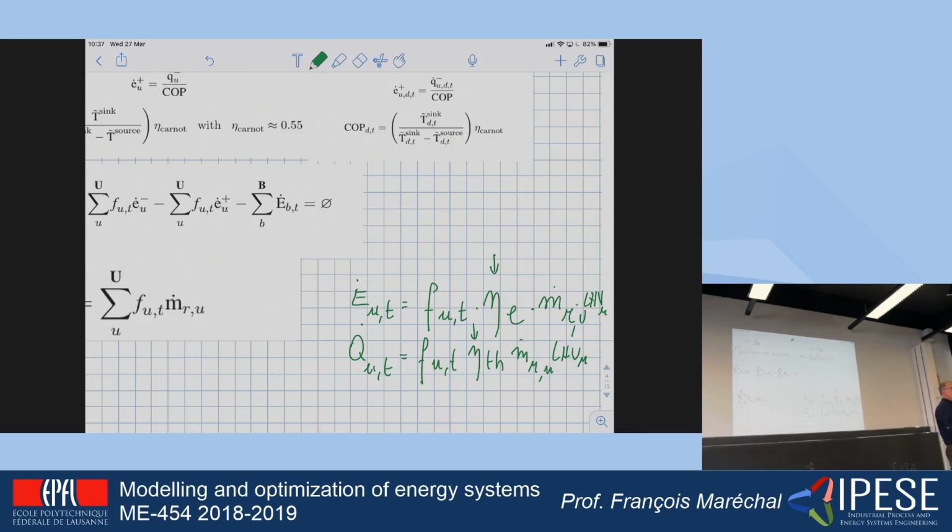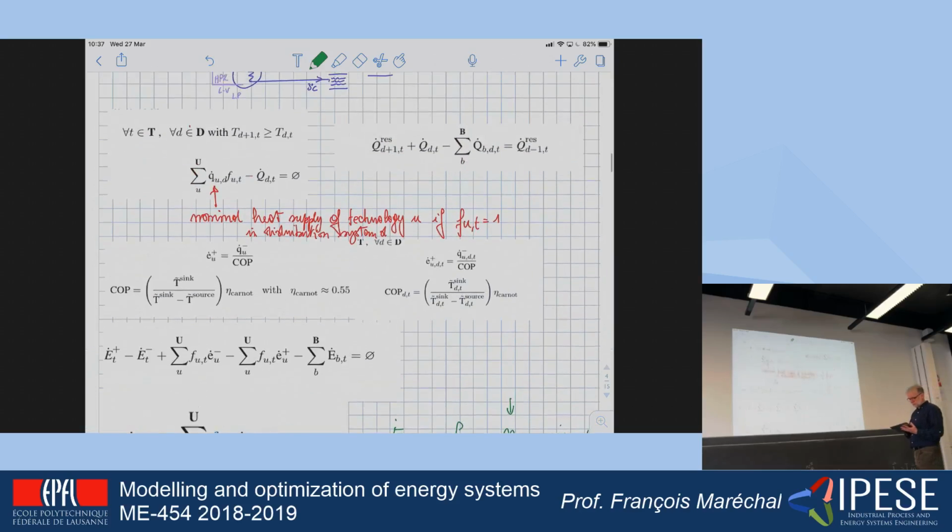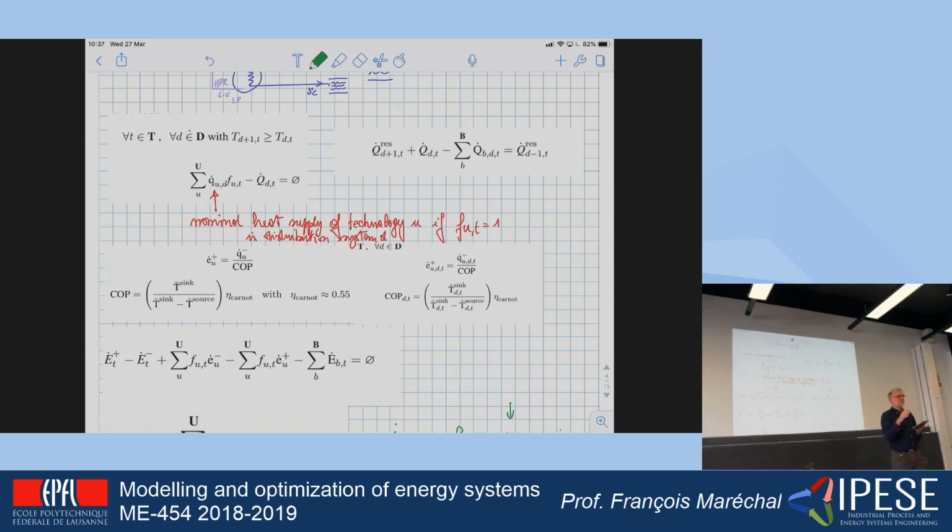And everything depends on the level of usage of the unit. So what I'm going to do is use a nominal condition which defines, for example, the typical flow or the best flow of gas in the gas turbine when the gas turbine is used in nominal condition, that I will multiply by a multiplication factor which is the level of usage of the unit, okay? So, which defines the part load of the operation of the unit.